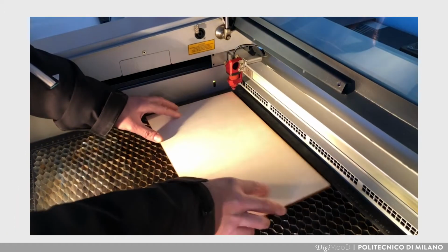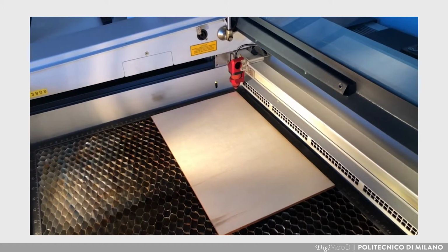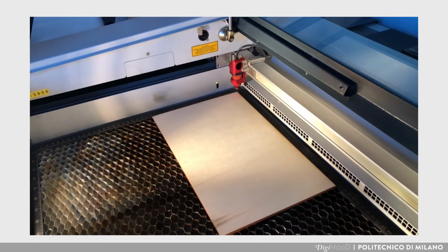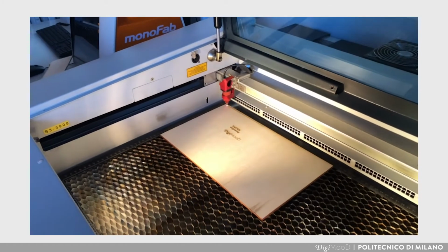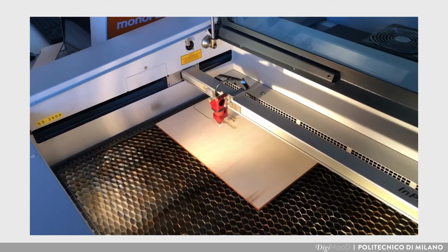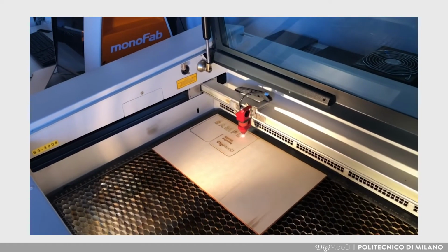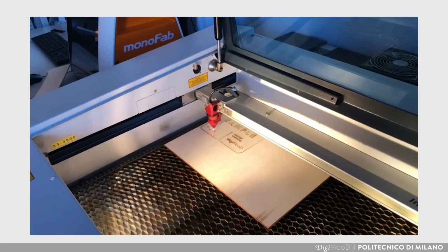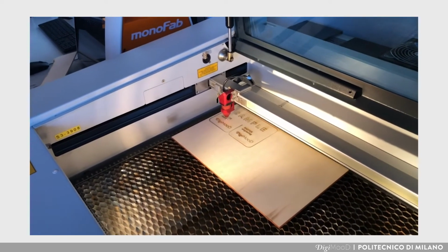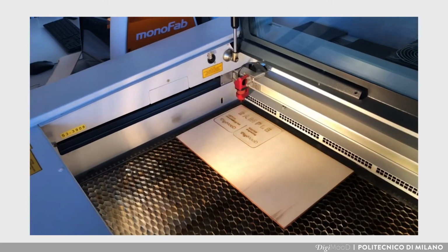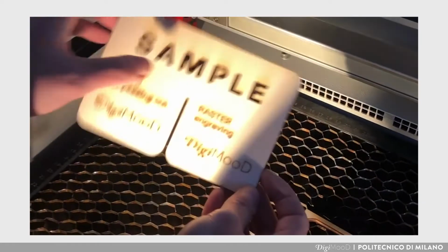You have to insert the material, for example plywood, on the top of the processing table and then press the Start button. The material does not have to be clamped and also does not have to be modified at the device. However, it's important that the material is completely flat and straightened out. The finished workpiece can be removed as soon as the laser process is completed, without reworking. Then the laser head traces the vector image and cuts the design out.